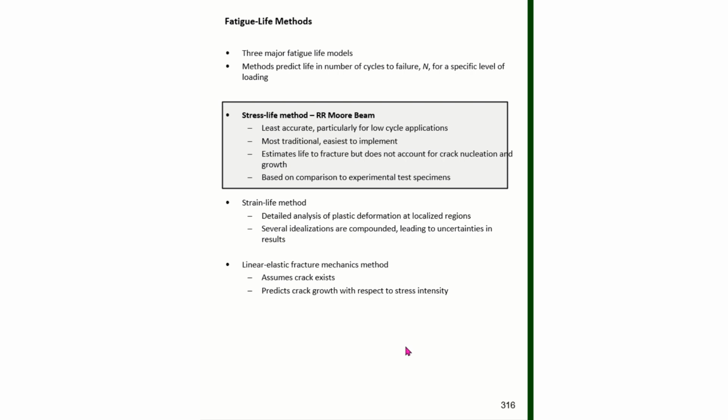It estimates the life to fracture, but does not account for crack nucleation and crack growth. And it's based on comparison to experimental test specimens. And it's mainly based on the idea of what we will call the RR Moore beam.